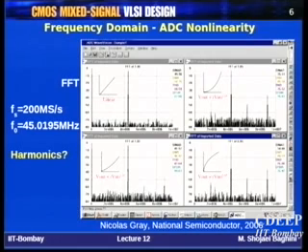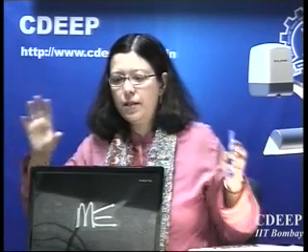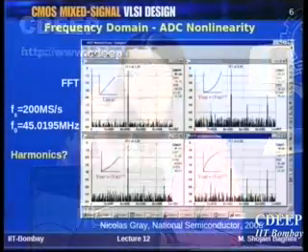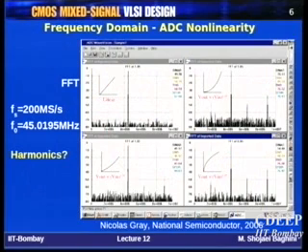See, when you look at THD, in THD you are calculating the RMS value of the entire nonlinearity, meaning the entire harmonic range. But usually all harmonics definitely don't have the same amplitudes. And it is important to know the contribution of the maximum harmonic, with maximum amplitude. So, this is a more particular definition, because that gives you an idea of really what is the difference between the main harmonic and the next strongest harmonic, and where it is located.